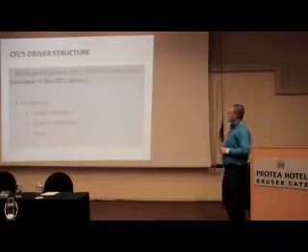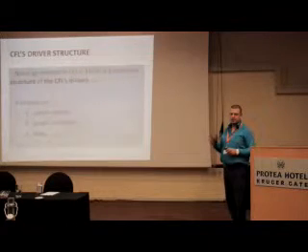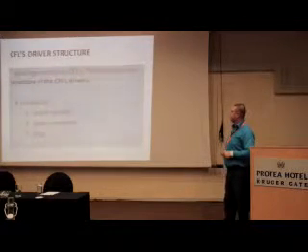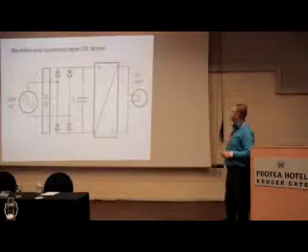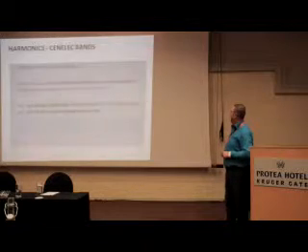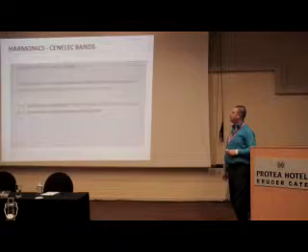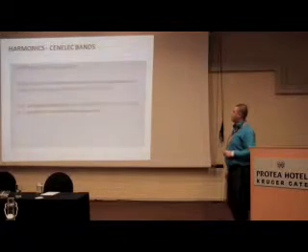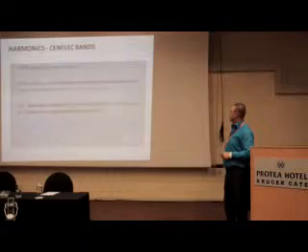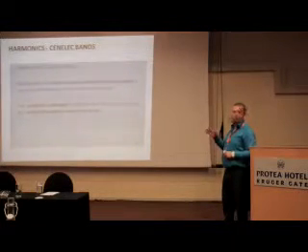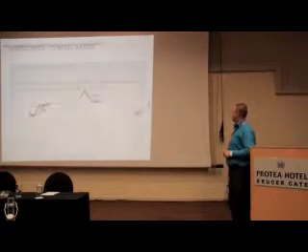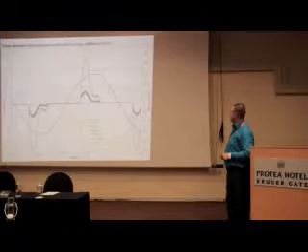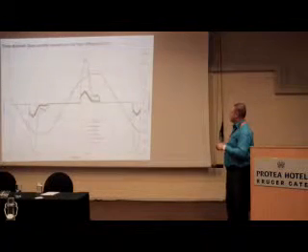Noise generation in CFLs: there is a common structure of the CFL drivers. The CFL driver consists of active rectifiers, power converters, and filters inside the CFL itself. This is how the rectifier and the converter type look. There were 4 types of CFLs tested, and we also did some extra analysis when we turned all 4 on together to show the harmonics. Here we show brand A, brand B, brand C, and brand E, and here all the brands together.